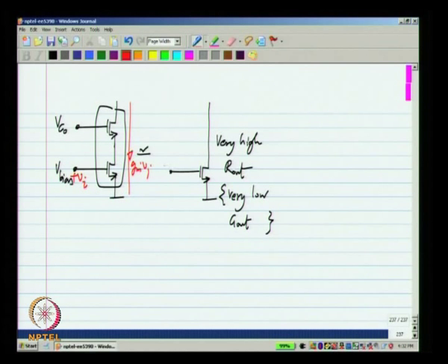This is the same as what we would have with the single transistor. The incremental current here is Gm times Vi. The only difference is that the output resistance is very high. So, in some ways it is reasonable to think of it as a single device while synthesizing circuits. After we have the circuits, we can analyze the complete circuit, including the effect of these different transistors.